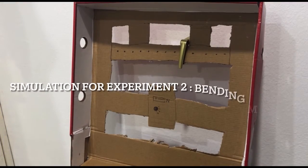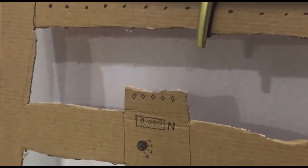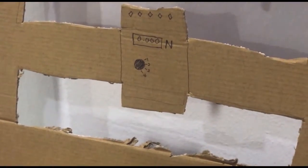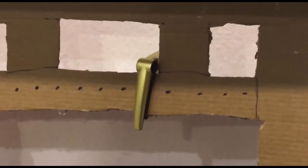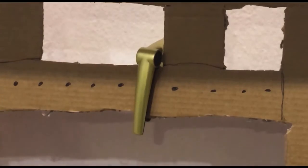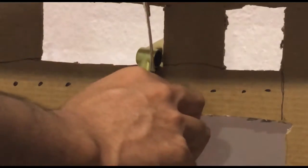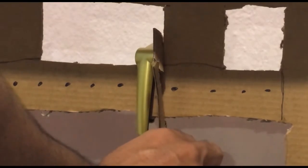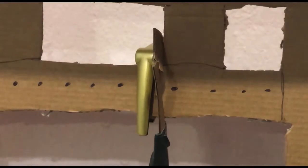First of all, check the digital force display meter reads 0 with no load. And then, place a hanger with a 100-gram mass at the section XX. After that, record the digital force display reading.